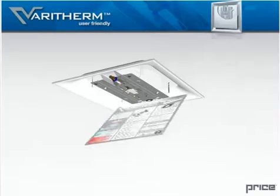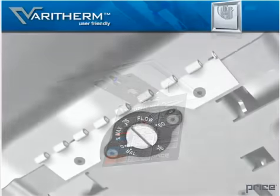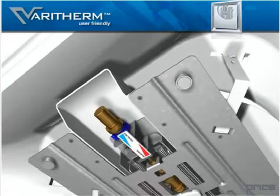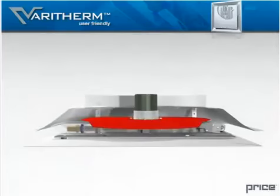Simply opening the plaque allows the user to make control adjustments. The plaque pivots securely on a solid hinge and is held closed by a set of powerful magnets. Easy-to-read gauges let you know what your settings are. Temperature is adjusted with the spin of a dial, and the minimum airflow setting is adjusted with the turn of a screw. The unit is also equipped with a forced open mode to assist in system balancing.